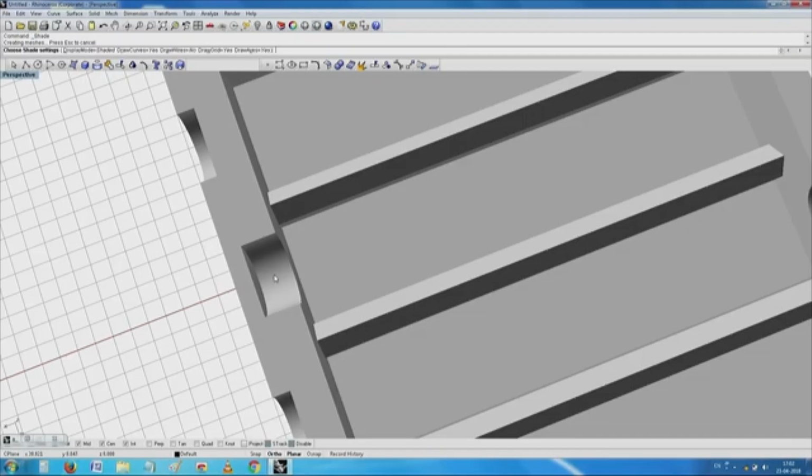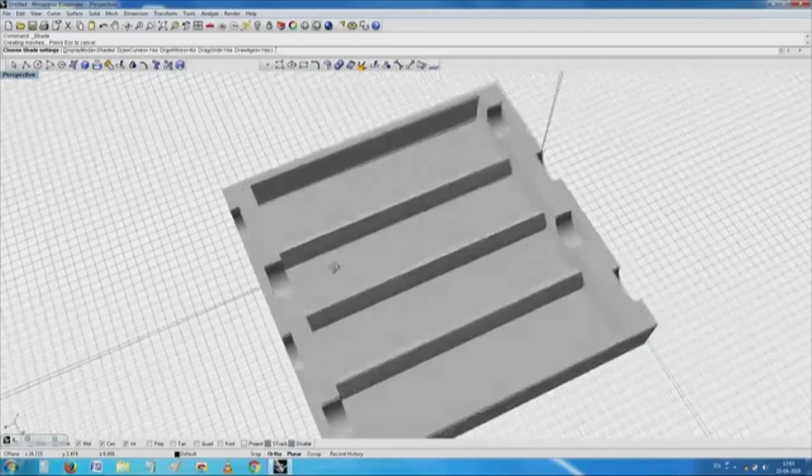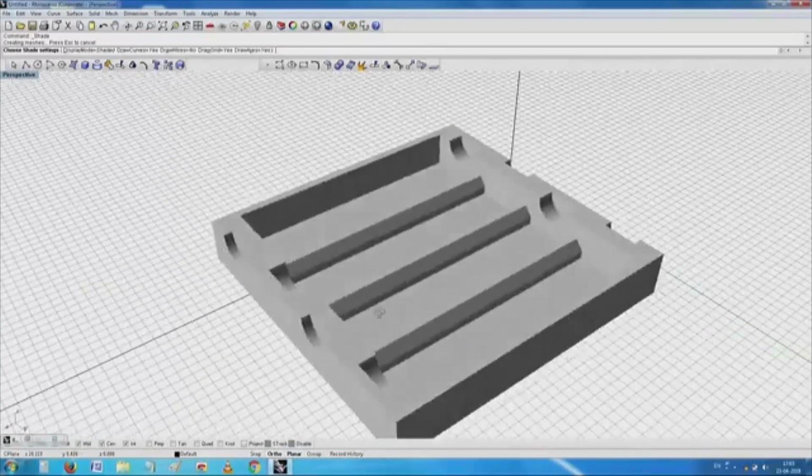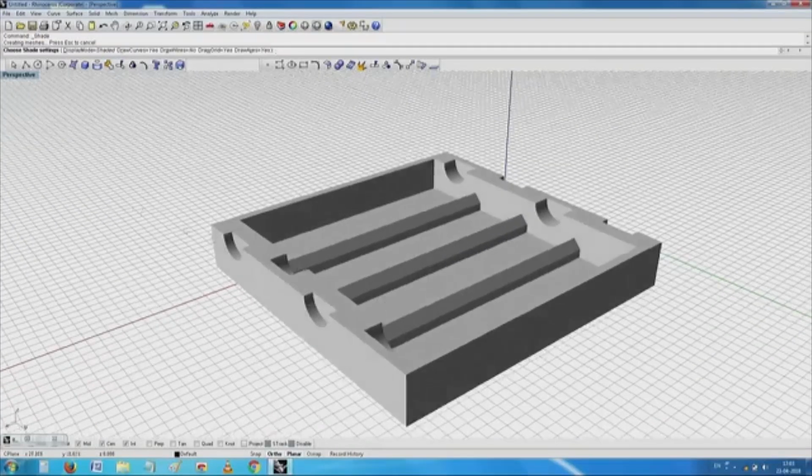So in the original model, if I create a space in which an electrical wire can be installed, it's possible for me, at least in some of the machines, to stop the machine and add the inserts as I like. In case that is not possible, we can probably make a through hole here and then do whatever operations we want to do. You have got this point.